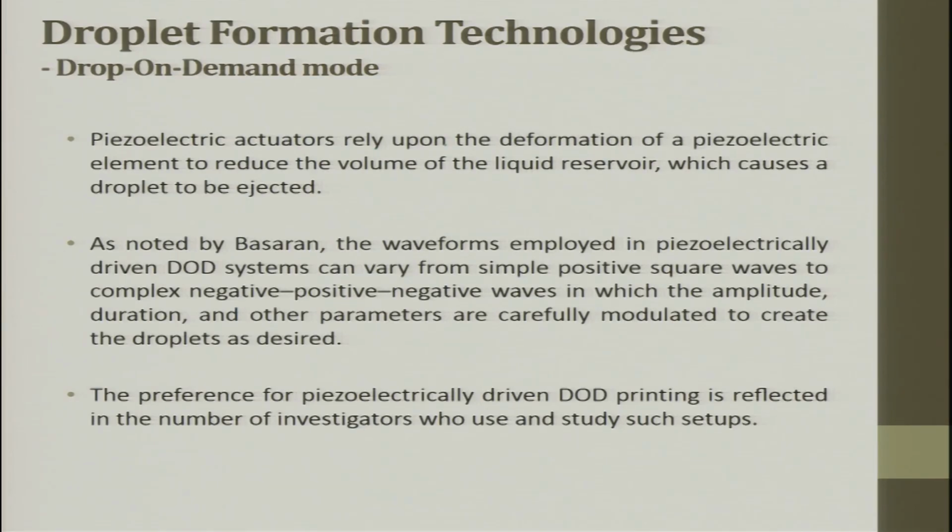Piezoelectric actuators rely upon the deformation of a piezo crystal element to reduce the volume of the liquid reservoir, which causes a droplet to be ejected. As noted by Basran, the waveform employed in piezoelectrically driven DOD systems can vary from a simple positive square wave to a complex negative-positive-negative wave, in which the amplitude, duration and other parameters are carefully modulated to create the droplet as desired.